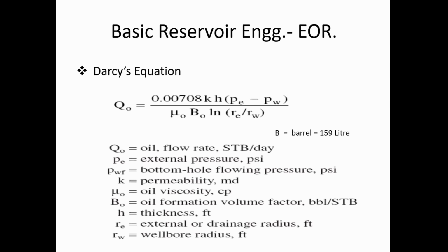The other factor that could be affected by tertiary recovery is the value of K. K is permeability. So permeability could also increase, especially if you have acidizing. These are also washing. If you wash the permeability from any debris, any precipitations, you will get better flow. So remember, what does tertiary recovery do for a Darcy equation?